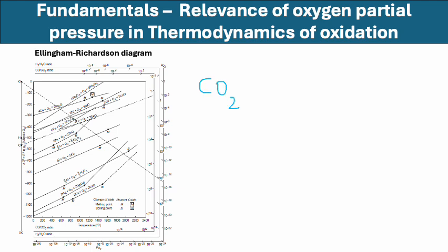There is something called supercritical carbon dioxide power generation technology. I have also given you a link to a write-up that talks about the supercritical CO2 reactors, and I have also attached a review paper on this topic, how it is coming up. It's a new technology, another clean energy technology. In this process, the oxidation takes place because the carbon dioxide dissociates into carbon monoxide plus oxygen, an atomic oxygen. This absorbs on the metal surface and it can oxidize.